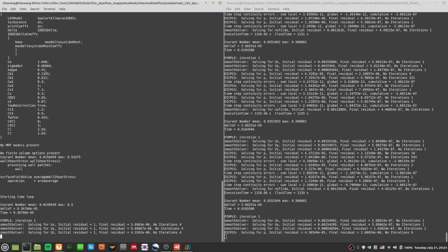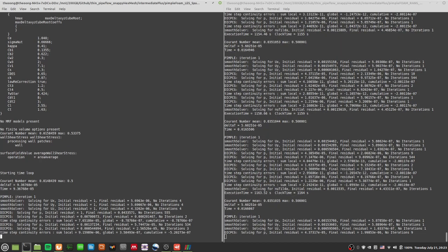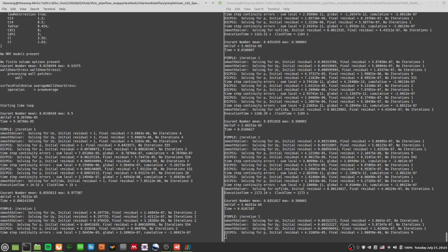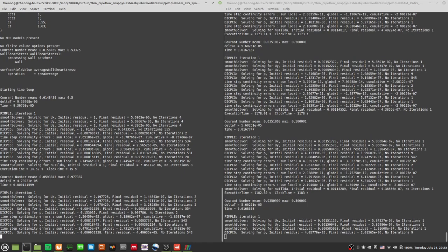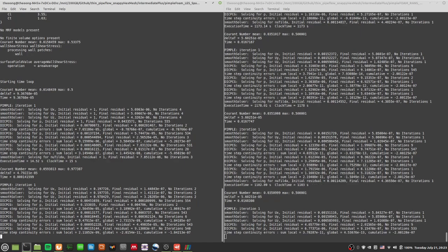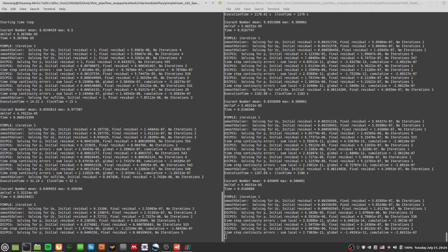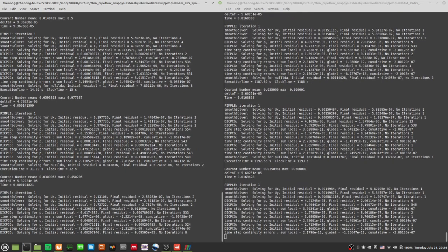Okay, there's nothing too much to do over here. There's very little work. Once you've done the Reynolds-averaged Navier-Stokes stuff, I mean the SpalartAllmaras or the kOmegaSSTIDDES, switching over in terms of syntax is pretty straightforward. Of course, you've got to make sure the mesh sizing is right. And for that, do go and look again at the Turbulence Modeling video series. I have a lot of videos detailing how to size your mesh properly, and these are good guidelines.